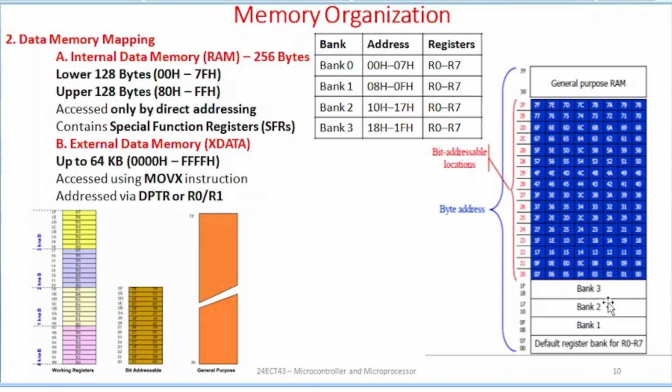The SFR space includes port latches, timers, and peripheral control registers. All the members of the 8051 family have the SFRs at the same SFR locations. There are 16 unique locations which can be accessed by bytes and also by bits. The SFR memory locations are above 80H.